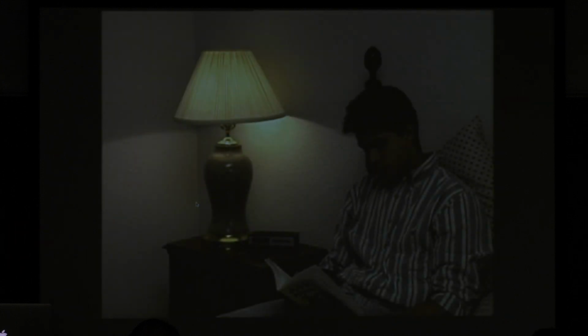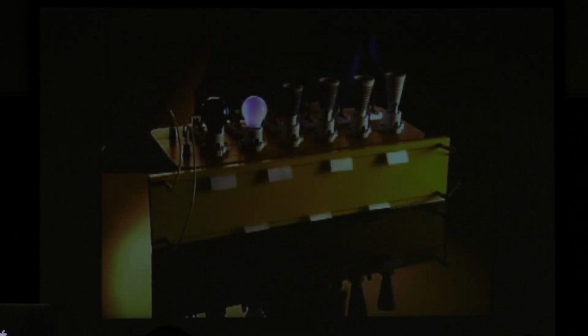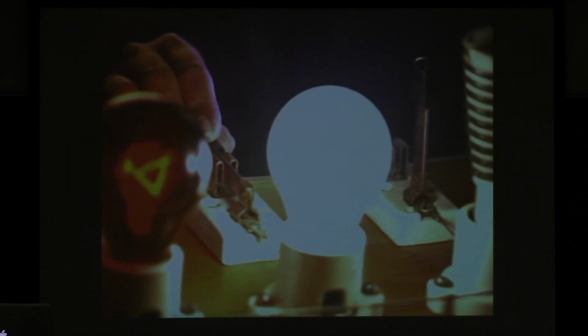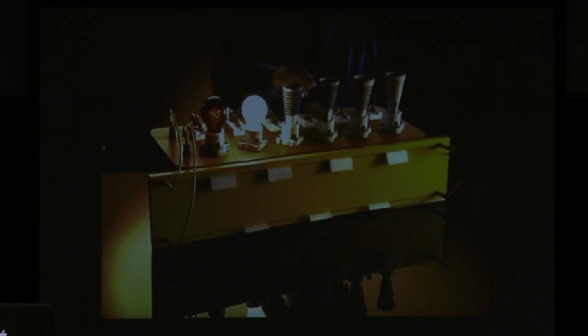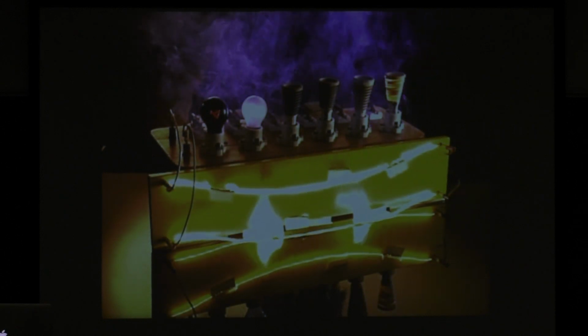Have you ever seen your house lights dim when you turned on a heater or a heavy appliance? We'll use this model of house wiring to demonstrate the effect. Two resistance wires will substitute for the normal copper wires used in a house to increase the effect. They run ordinary household current into this bank of lamps and heaters, which can be switched on and off individually. We'll first switch on the lamps. Then heaters will be switched on one at a time. When enough heaters are added to the line, the lamps dim. The electrical energy lost in the wires which deliver the current is dissipated as heat.